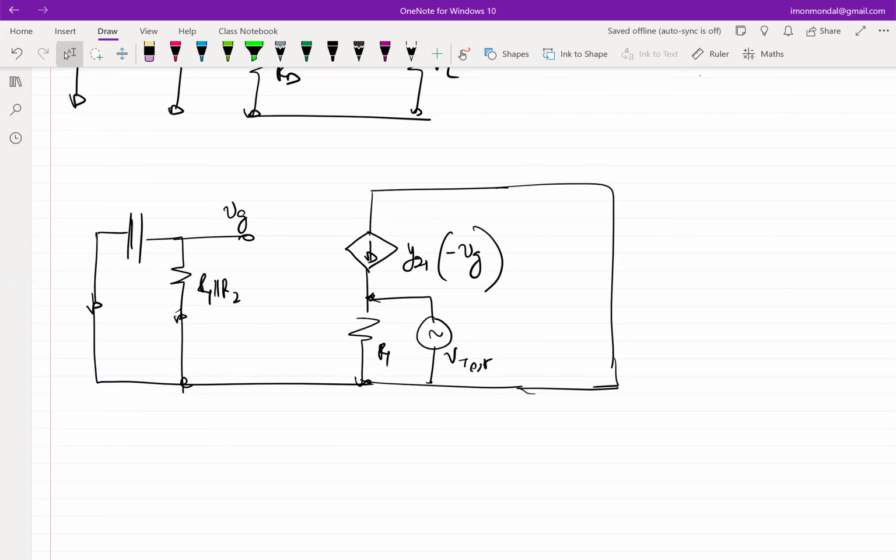Yeah, VG is zero, obviously, right? Because in order to have VG be non-zero, some current has to flow through this, but there is no way that current can flow out. So no current can flow through this. Effectively, impedance looking in this side will be infinite, so no current will flow through this, so VG will be zero. So if VG is zero, essentially this goes off, right?